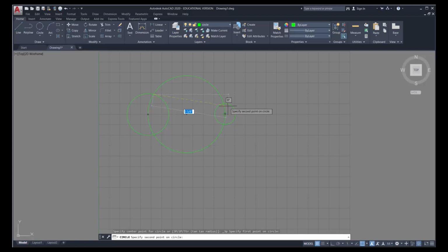There's point 1. I'm going to click on this intersection, which is on the other part of the circle. Now if I click on any other intersection here, it's going to make the exact same circle I made before. So you can see what's happening as I stretch the mouse. It's looking for that third point to make an arc that fulfills the requirement of all 3 points that I'm defining on the same arc. So I'll just pick a point anywhere. And there we have it.